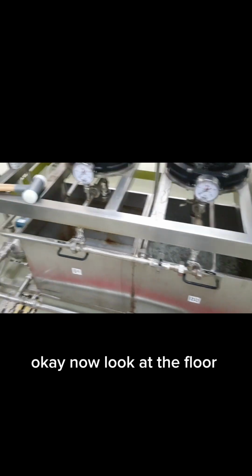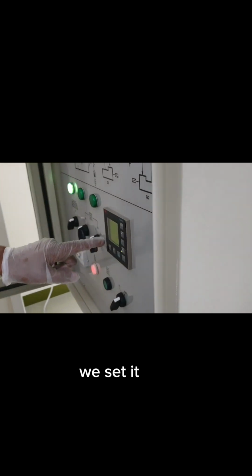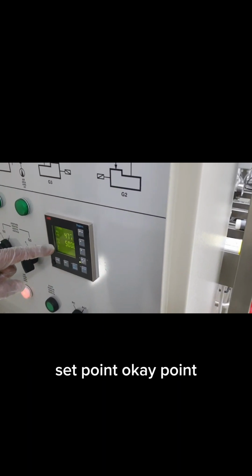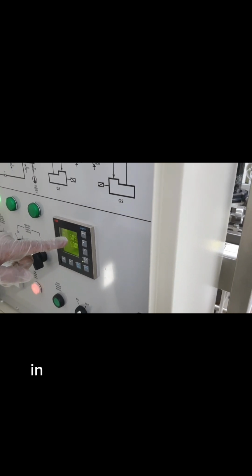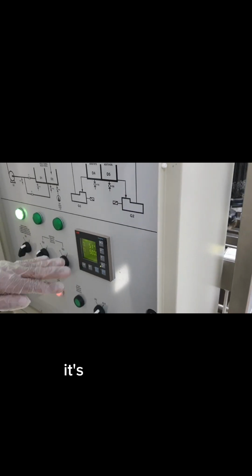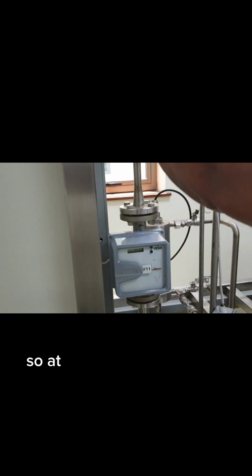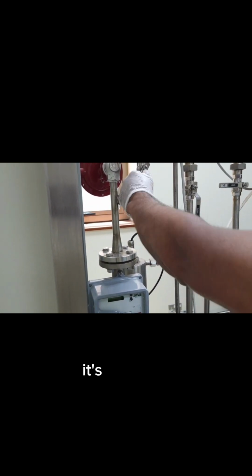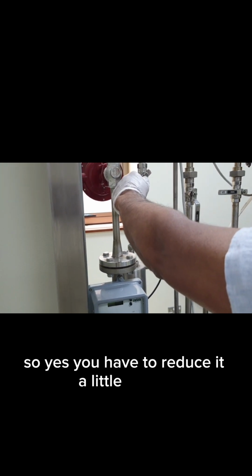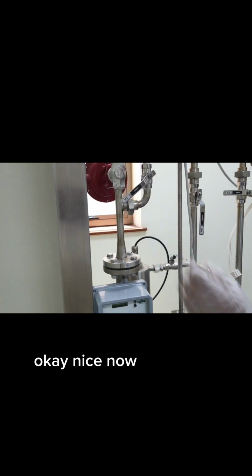Now look at the flow. Now it's almost 500, because in the beginning we set the set point, liters per hour, to 500. So it's attaining that point now. In the beginning it was low. Now at 500 you can reduce a little bit. If you open more, it's going up. So you have to reduce it a little bit like this. Now the flow is very good.